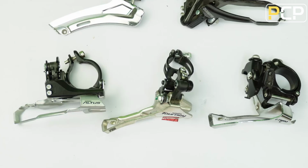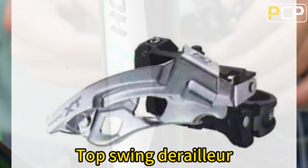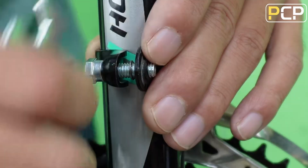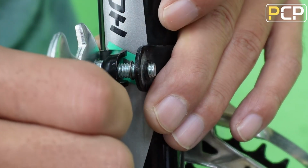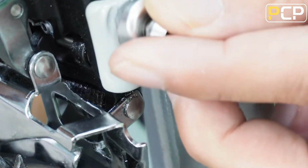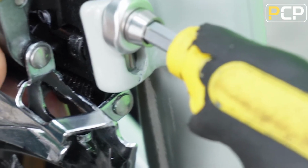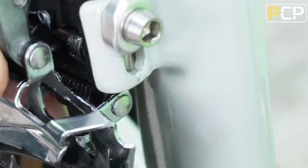The front derailleur is mainly divided into 4 types, which are top swing type, bottom swing type, e-top swing type, and direct mount type. The guide plate of the top swing derailleur swings on the upper side of the mounting ring. Based on the clamp position, the moving part of the top swing guide plate is located higher than that of the bottom swing derailleur. Besides that, the connecting part of the top swing derailleur is shorter and the stiffness is higher, so the shifting speed is quicker than that of the bottom swing derailleur.